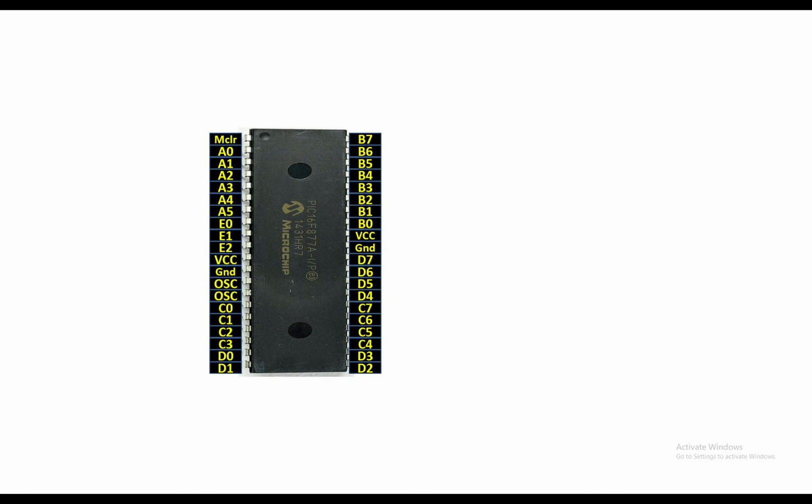First of all, set up the hardware, which is just a basic LED connection with the PIC. So I have this one PIC16F877A DIP version having 40 pins, and this is the LED I'm going to use, 5mm crystal type, having 2 pins, one longer, one shorter. Longer is always the power and shorter is always the ground. First of all, connect the ground pin directly with the ground of your PIC.